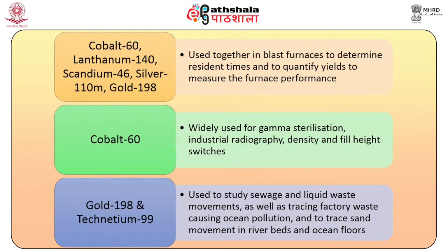Cobalt-60, lanthanum-140, scandium-46, silver-110m, and gold-198, used together in blast furnaces to determine residence times and to quantify yields to measure the furnace performance. Cobalt-60, widely used for gamma sterilization, industrial radiography, density and fill height switches.